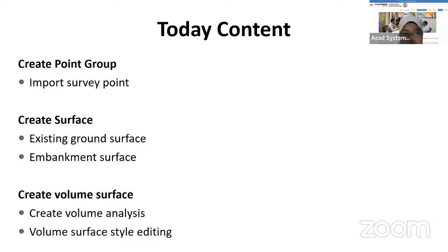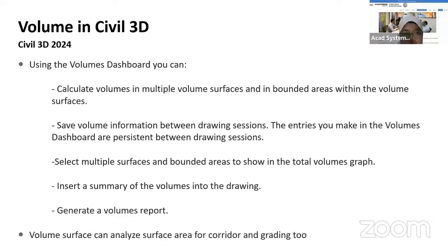Okay, what is the dashboard to create volume analysis? Using the volume dashboard, you can calculate the volume in multiple volume surfaces and bounded areas. With the volume dashboard, you cannot just have one volume analysis, you can have several in one dashboard within one project. And then it saves volume information between the drawing sessions.